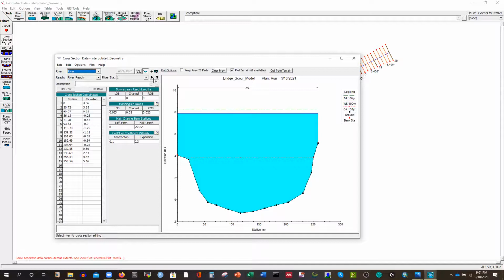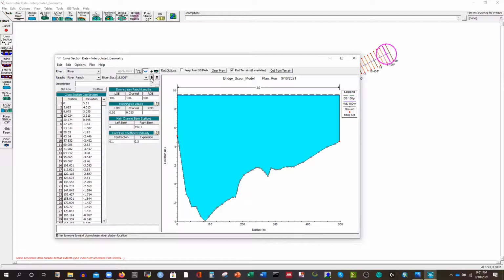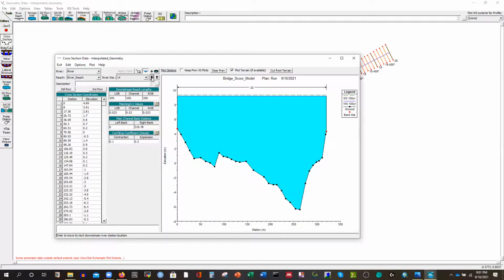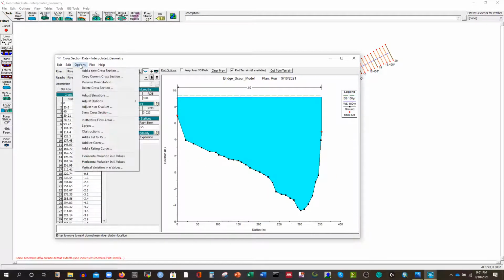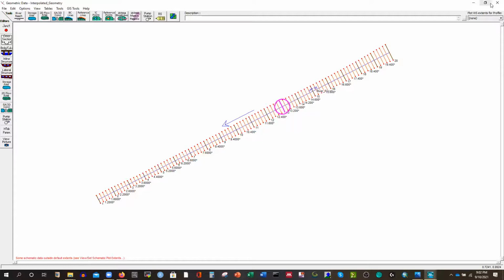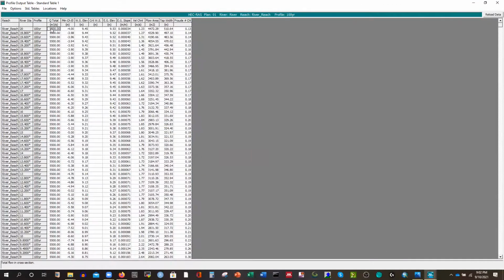This is the most downstream one, and if you click there, you can go to upstream, and you can go to the next cross section, because we interpolated it is just 19.8, and then it is just giving the IDs, and you can see we have this water, and you can see the velocity profile. If you want to see the velocity profile, you have to go to options, and then you have to select that variables, right? And then we can see, I'll show you how to do that. I'm just showing how to even see the result. If you want to see the result as summary, you can click there, the table. It will show you the table values for each of these. See the profile, we have one profile.